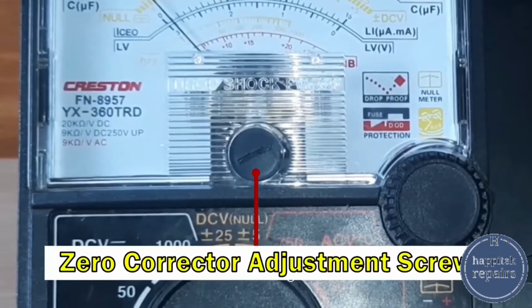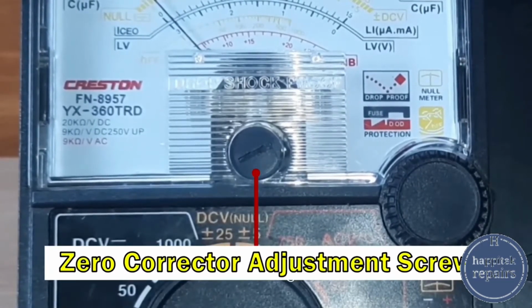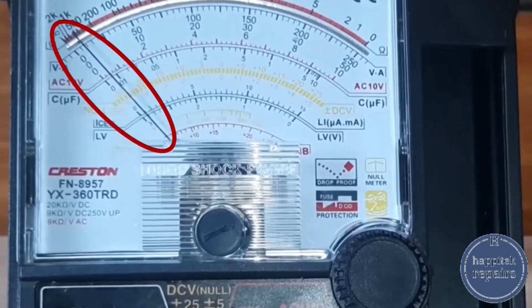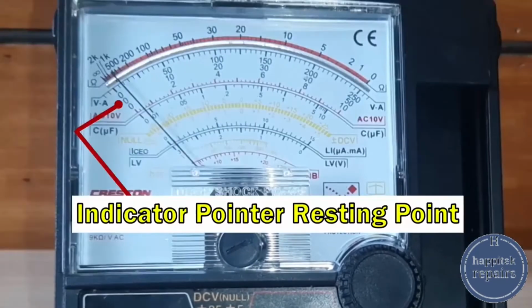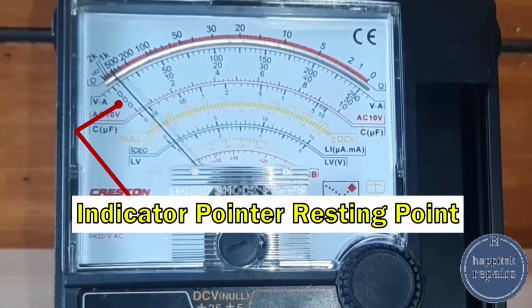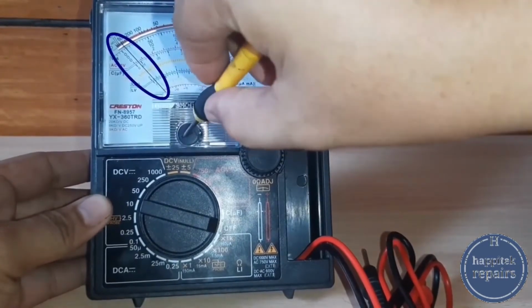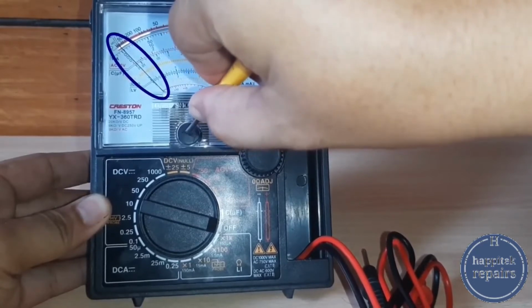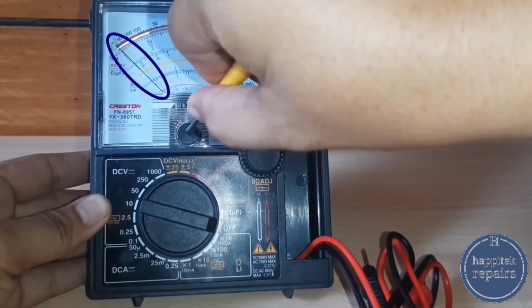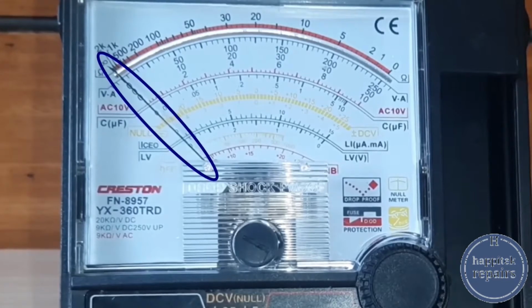Then this one is called the zero corrector adjustment screw. It is used to adjust the pointer to 0 at the left side, where we can see a space at 0. To adjust this, we turn it in a clockwise direction until the pointer reaches 0. Always bear in mind that the pointer must be aligned to 0 at the left side before using the meter for the tester to give accurate measurements.